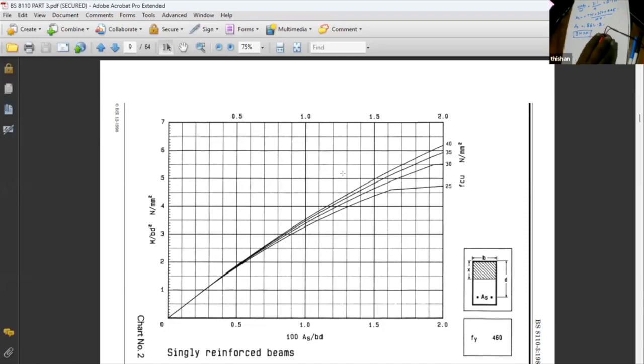And for most single reinforced beams, the grade of concrete does not matter. So there's no point in using any concrete stronger than 30 megapascal in a slab, because in the slab we cast the beams together. So never ever use anything more than 30 megapascal in a slab. That's the theory. That's how I design, so that's how I get very economical designs. I never use anything more than 30 megapascal in a slab.